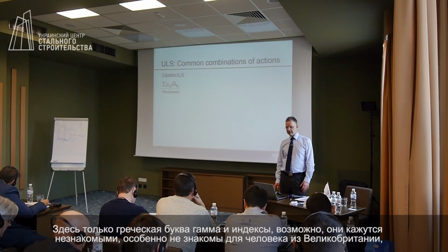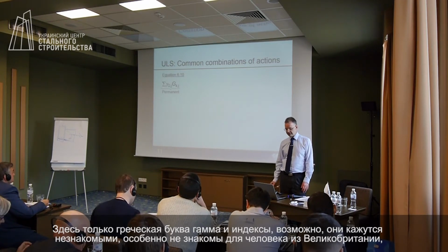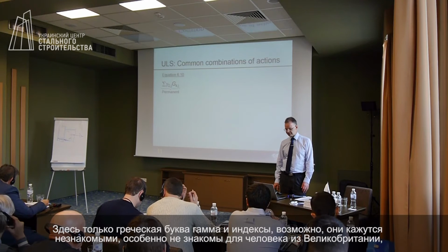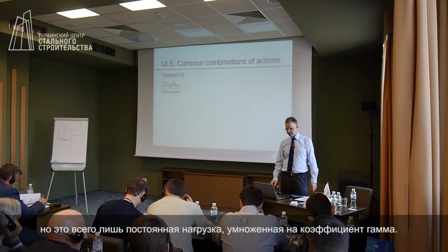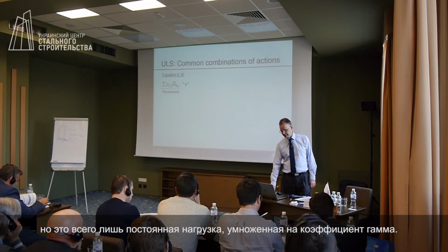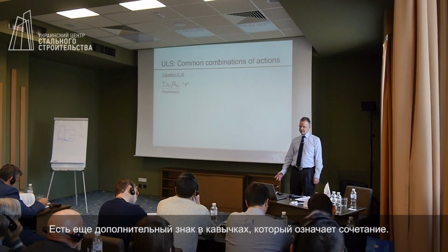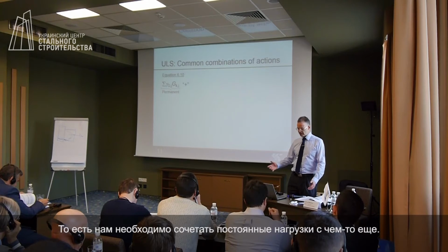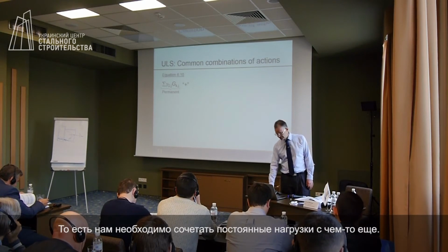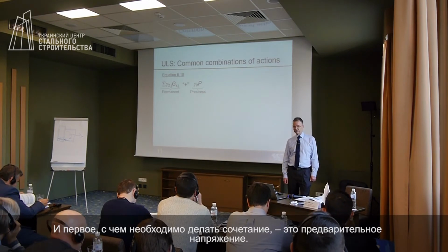So I appreciate there is Greek, gamma, there are subscripts. It perhaps does not look familiar. Certainly it doesn't look familiar to a person from the UK, but this is just the permanent actions multiplied by a gamma factor. And the addition sign in inverted commas means combine with. So we are to combine the permanent actions with something else. And the first thing that we are to combine with is pre-stress.